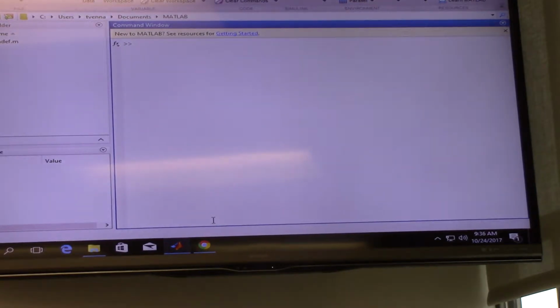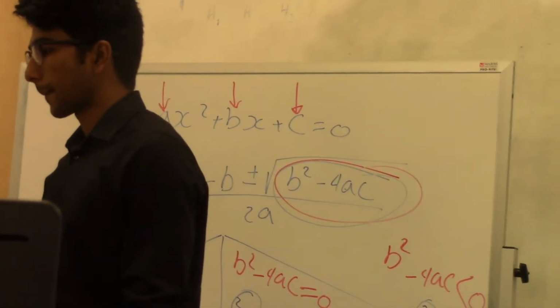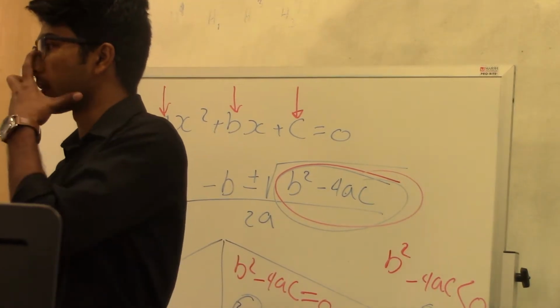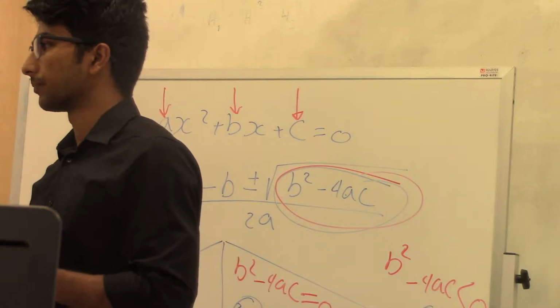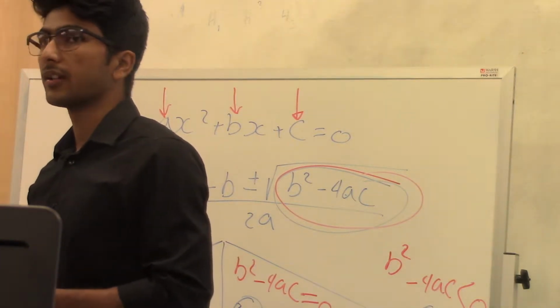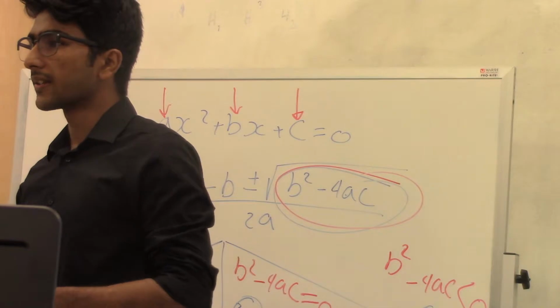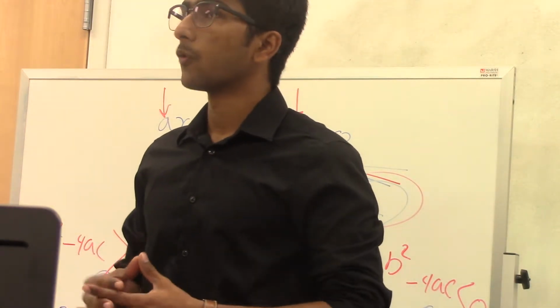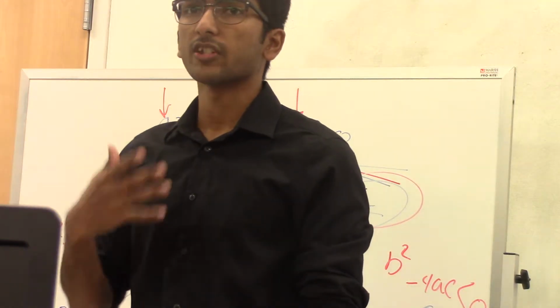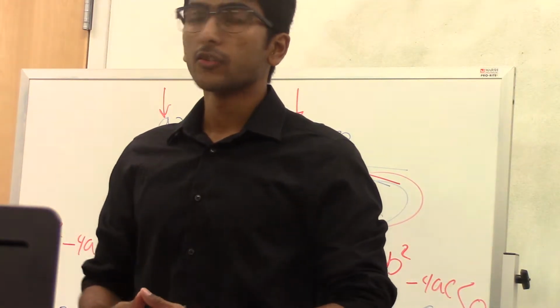So what is forward kinematics? Anyone? What is inverse kinematics? To translate the point or rotate the point on the particular. Yeah, those are transformations. So when you're talking about manipulators, there are basically two things that you need to calculate: forward and inverse kinematics. When you have a set of joints that needs to be turned into a specific angle, then you need to calculate what will be the end effector position in three-dimensional space. That is forward kinematics.